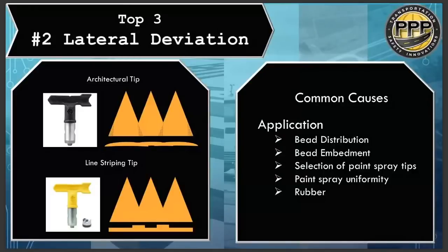Has anyone? Hang on. Go ahead. Type 3 beads experienced a washout, i.e. yellow washing out to white? The question is has anyone had an issue with type 3 beads washing out the yellow? Yeah, I can say that is mostly caused because there's not a good intimate connection between the bead and the yellow paint. In my experience it's a pigment issue potentially with the paint, or the bead is too high, which is pretty darn common out there because the paint's not being put down thick enough. So it's either paint quality or the bead embedment issue.